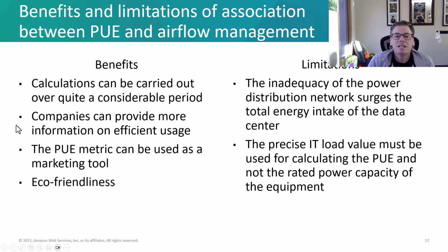All right, if we look at some of the benefits that we might see with our PUE and airflow, it tells us the benefits are that we can do the calculations over a big time period. It can give us a lot of information about energy efficiency, and it's relatively eco-friendly. And again, they tell us, hey, this is a marketing tool, of course. Some of the limitations: inadequacy of the power distribution network and surges can skew the data a little bit. And it tells us that the precise IT load value has to be used for calculating the PUE, and not the rated power capacity of the equipment.